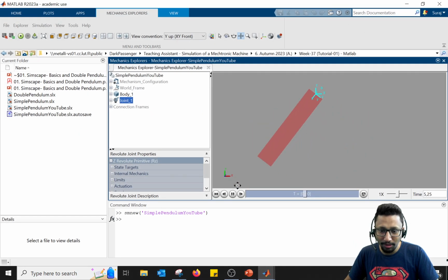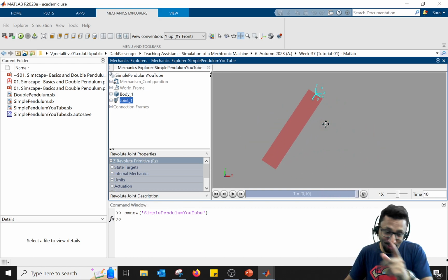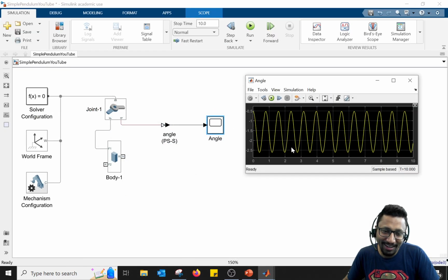Now if you see, the animation looks much smoother. If you want, you can compare it. You can rewind, go back to the last animation that I showed in the video and then compare it with this one. But if you don't trust me, see the plot itself. The plot now is so smooth here. You can see that, right? So clearly, by changing the solver setting, the simulation was affected so much, right? So that's very important for you to know.